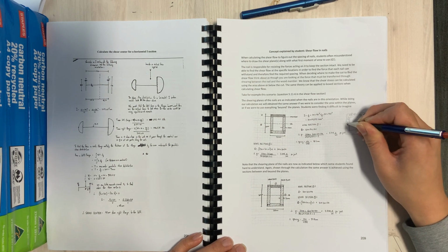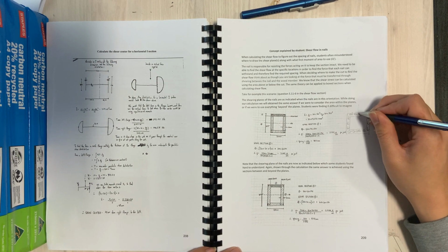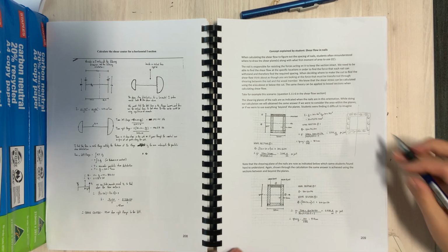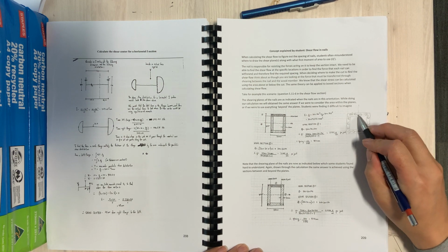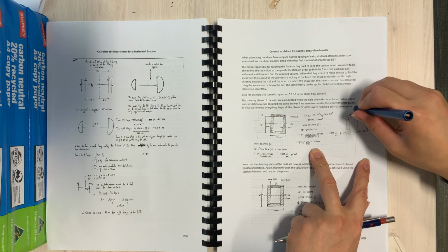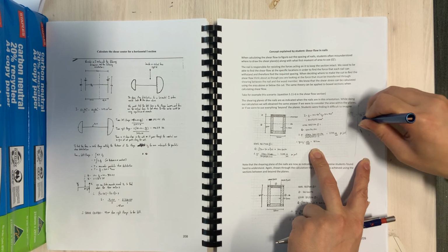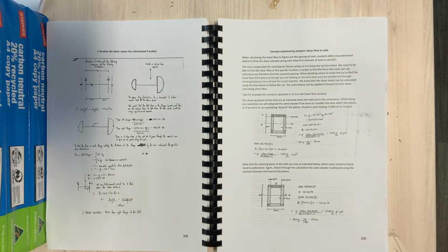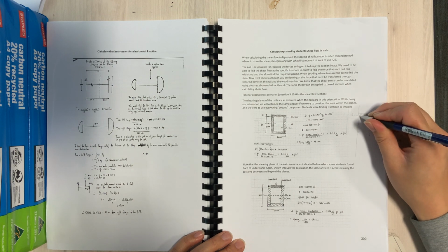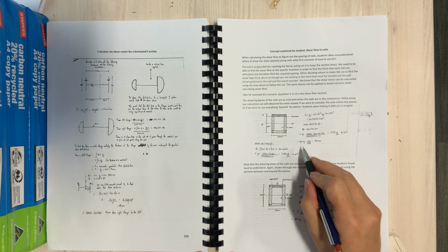So I'm sure Lucas would have covered that. A bit of thought tells you that's what you would expect the shear flow to be doing, the vertical members taking the shear and these being the horizontal. So we can take that bit out, and if we did our calculation based just on that, we would get the shear flow acting through the shearing plane of the nail, and then we would be able to work out the spacing.